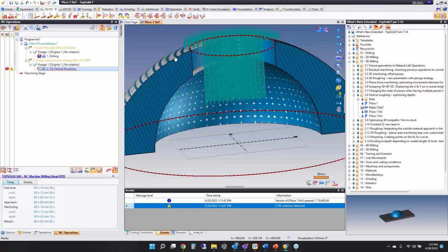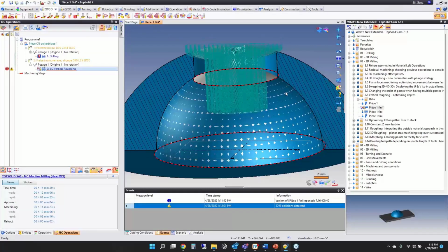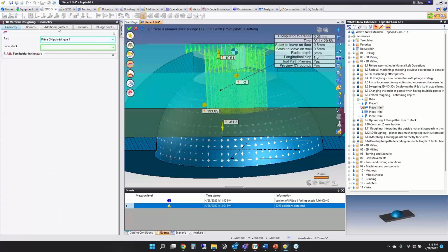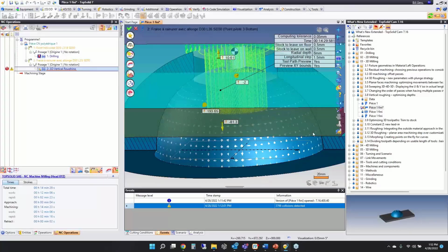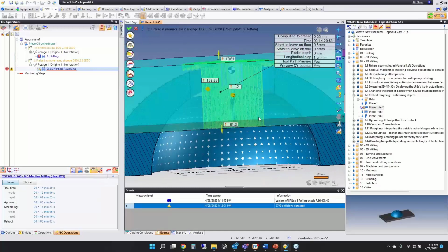So in vertical roughing, there was really no easy way to control that drilling over depth. Maybe we did it with extra geometry. I don't remember. You could add an additional surface as something to stop it from going through, but you had to do manual work there. If you happen to have already roughed out this side and did a repositioning of it, it requires you to do extra work to really control the vertical roughing.